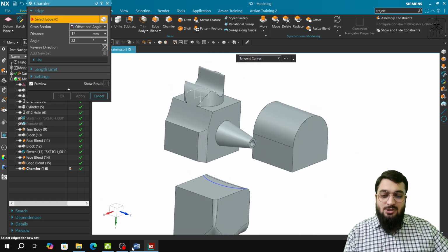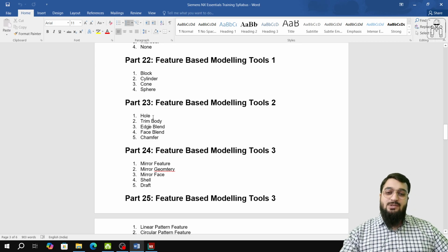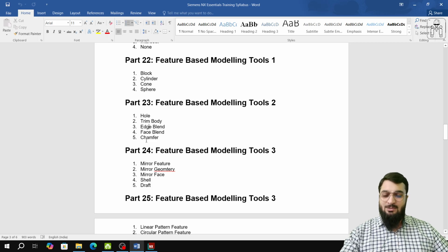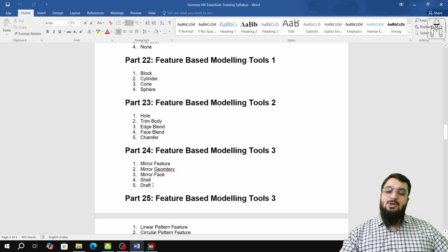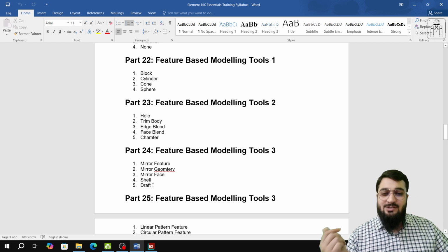So just to summarize, we have discussed the hole, and the three parameters that are required: the point, the vector, and the body from which it is to be subtracted. After that, the depth of the hole and the radius of the hole. After that, what is required is the type of hole, that is, countersunk, taper, drill, with respect to the drill or the screw clearance, etc.